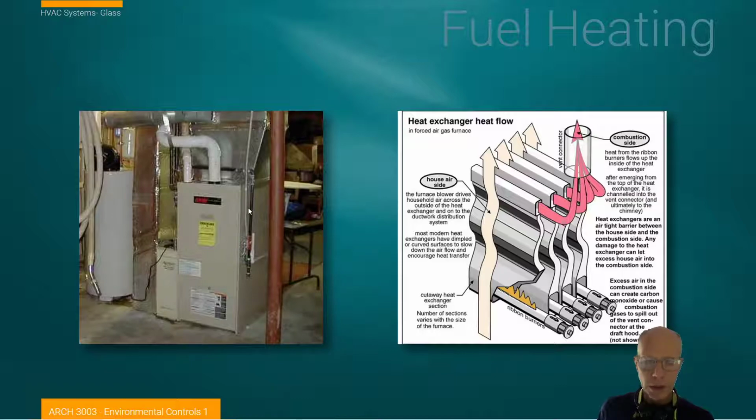So a little bit about what's inside of natural gas heating systems. There's a heat exchanger. I just wanted to expose you to this. This is a device you would typically see in a basement. These are the gases, the natural gas. This is a fresh air intake. It goes in and passes through a heat exchanger. Down at the bottom, it meets the fuel and is in combustion, and it snakes its way up through the heat exchanger until it's exhausted through the smaller pipe.